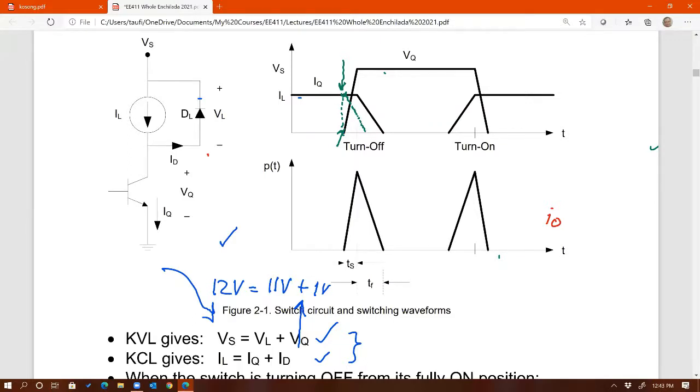If I do that, notice that I'm also preventing the two peaks from occurring at the same time, right? You agree with that assessment? Yes? Okay. So now you know the two methods of minimizing switching losses, or in this case, turn off. Number one, by slowing down the rate of rise of the voltage across the switch as it's turning off. Number two, by allowing current through the switch to also change while the voltage across the switch is changing.